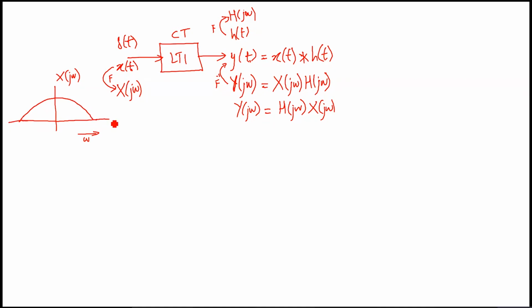Typically you will notice that for a continuous-time non-periodic signal, the frequency content forms sort of a continuum. That's very typical. And a real signal always ends up giving you an even plot of X(jω) across this y-axis right here. This y-axis, which is omega equal to 0, represents your DC or zero frequency. And each point on this axis, I think I have talked about it earlier also, actually refers to a complex exponential. For example, if we take any point right here, which is omega 1, and we see the value for that, it comes out to be, let's say, some value A.